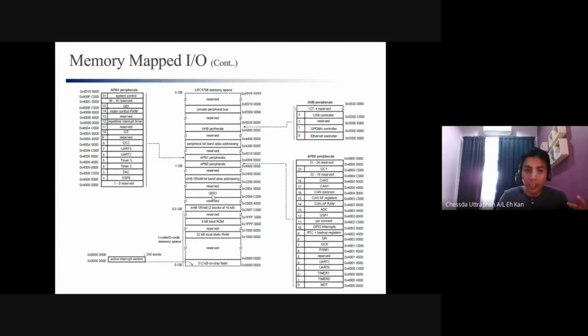All right. You have the keyboard or switches or LED, so you need to use this range of addresses. All right. So that the microcontroller knows, oh, this address is my input, this address is my output. Okay. And what is this? This is actually this part, because there are many things inside. This is for peripheral, right?